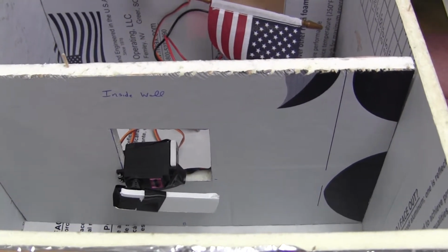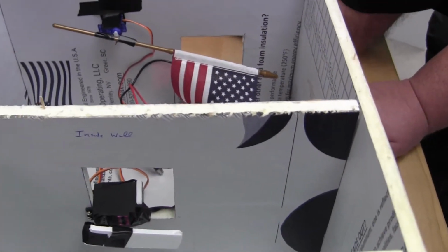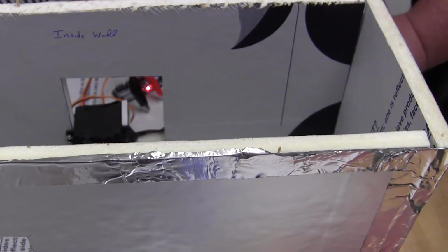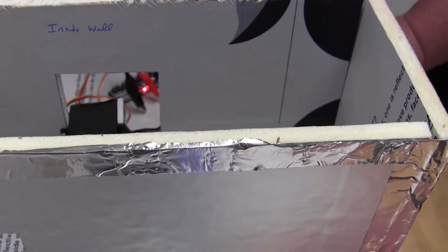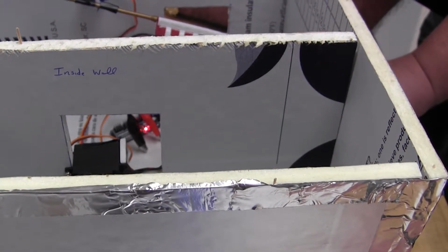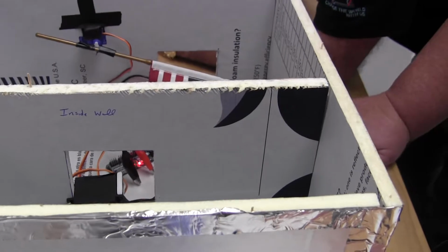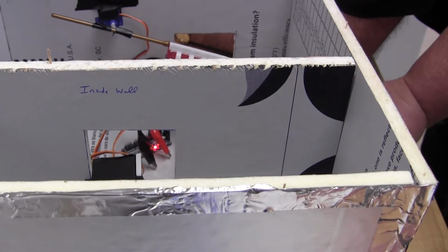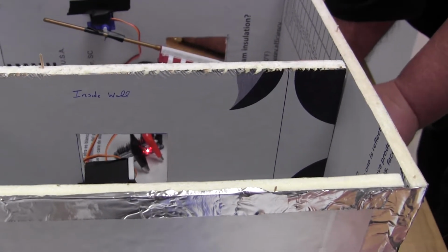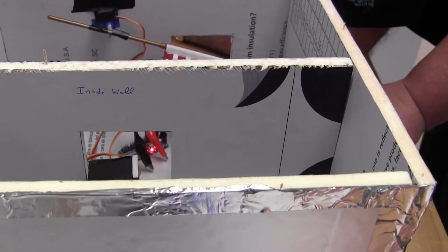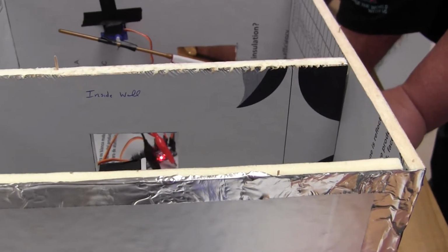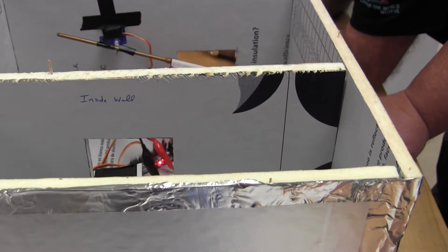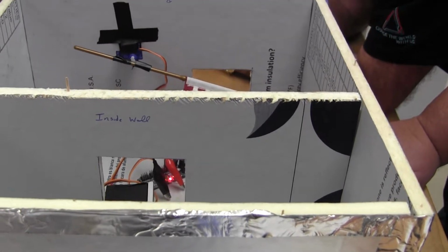Okay, so we're seeing right now the kind of things that cause demos to go to hell in a handbasket. You chose to use alligator clips, right? Why? It's been working flawlessly. Yeah, but it's that kind of haphazard connection that will cause you problems and turn a very successful demonstration into a POS. Okay? Don't do those things to yourself. Make hard connections. Over here, you're plugged in. Here, you're clipped on. Not good.